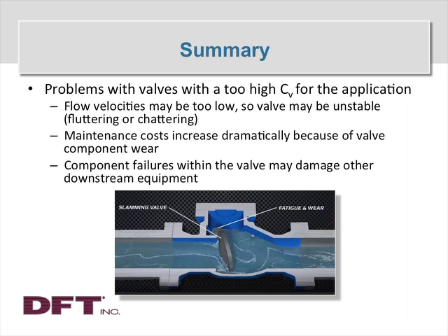And if you have an extreme condition to consider that by itself might be forcing 2 times your normal flow rate through the valve, like an emergency situation where you've got to put extra water through that valve, then the lower normal condition may be causing you problems with your check valves. And that's something that you need to be concerned about.